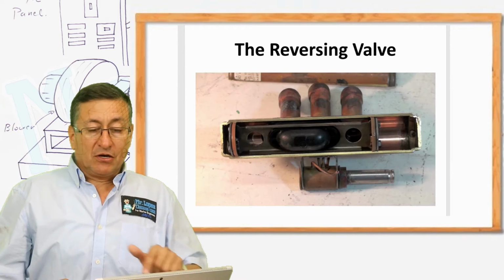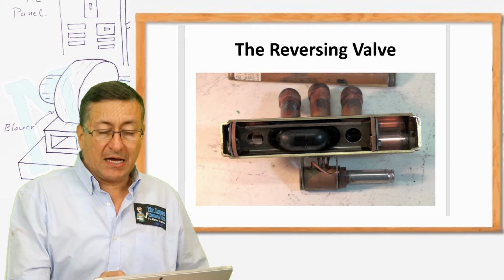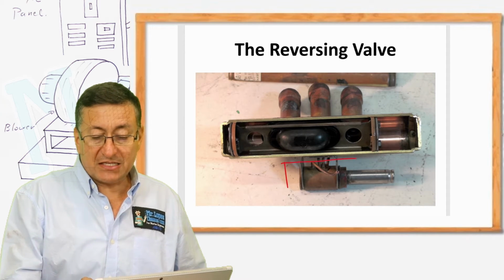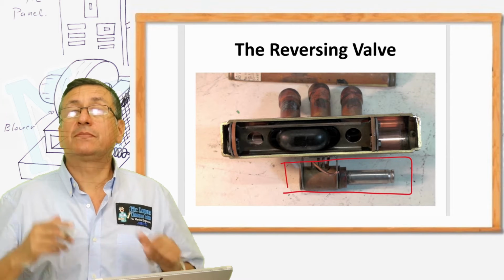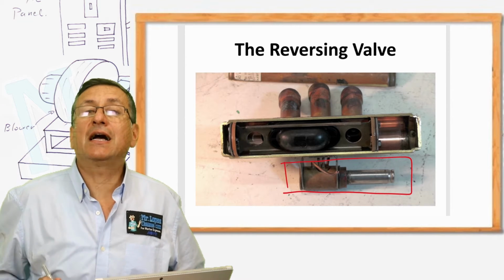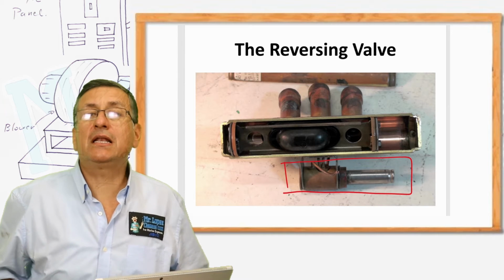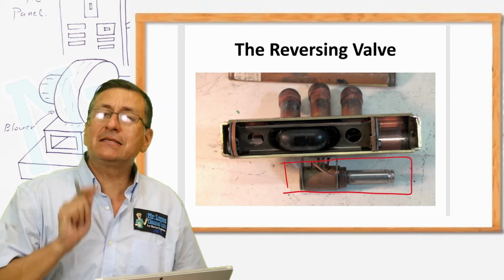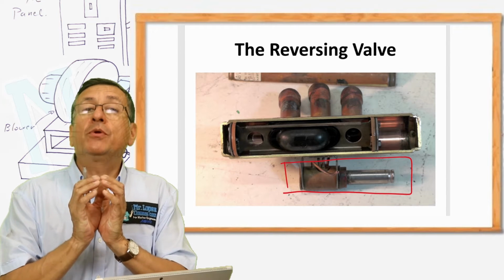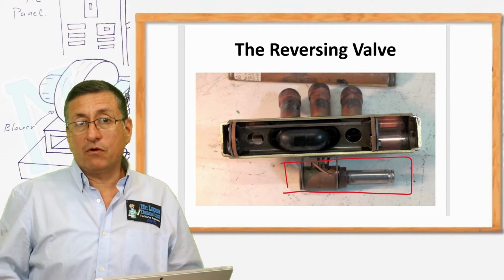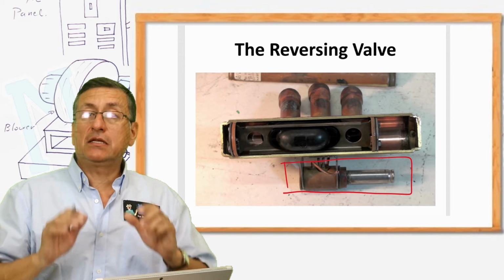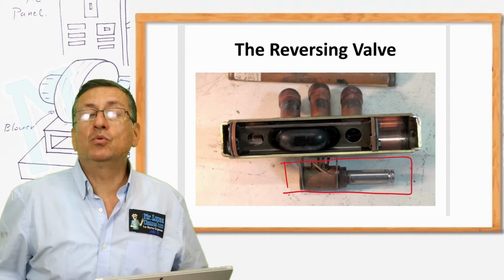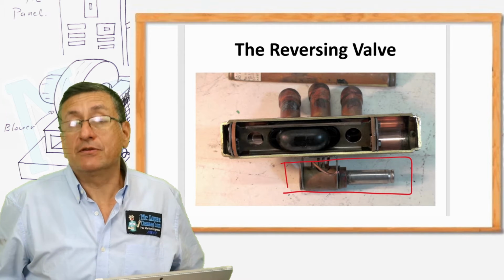Yes, this is possible because of this valve and this piece of metal in the middle, and it's possible because of this solenoid. The solenoid is activated with a signal between 24 volts AC and 30 volts AC. That signal is coming from the computer. You remember the main board of the air conditioning system located in the control box. Normally the control box is close to the condenser.